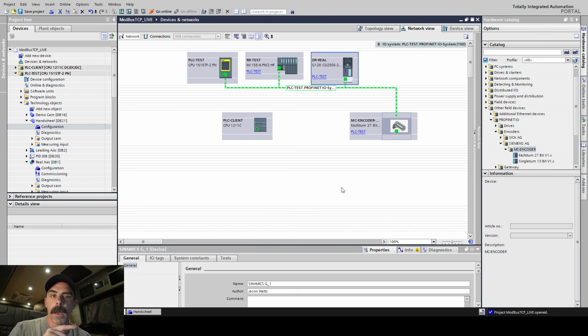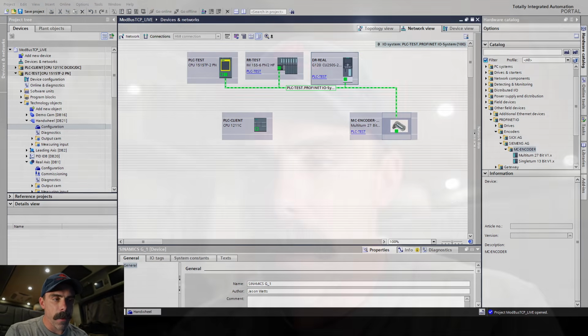So you've got, at really bad resolution, an analog tachometer, but you only need to use an analog input. It's going to be an analog input based on the speed. Then you have a couple of types of incremental encoders that we talked about. You're going to need to bring that into your system through some sort of device.